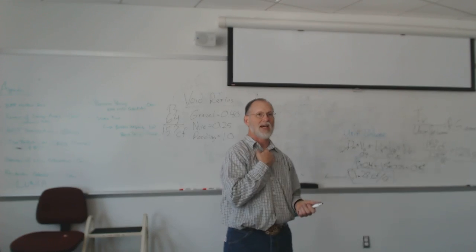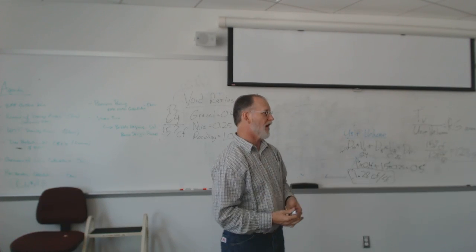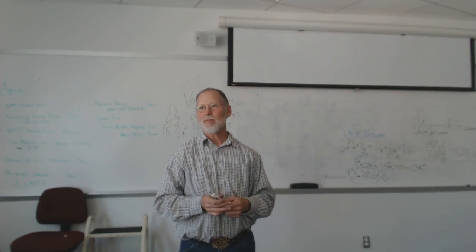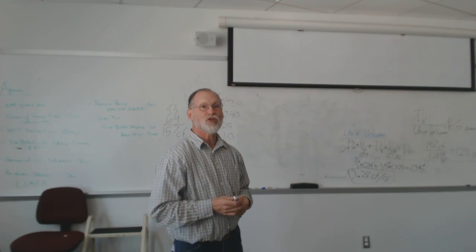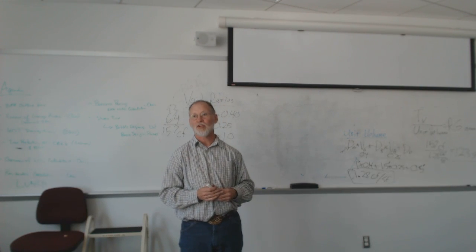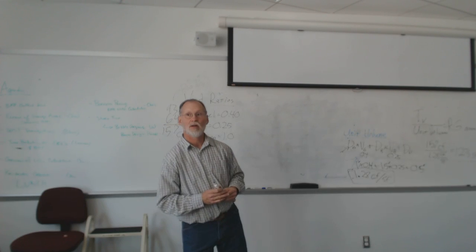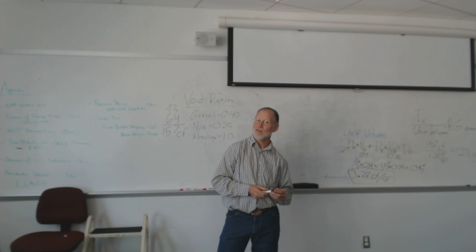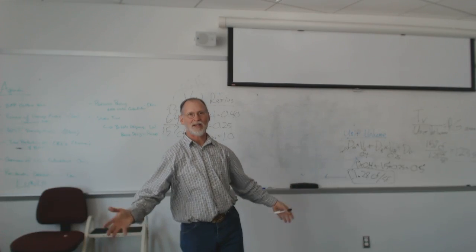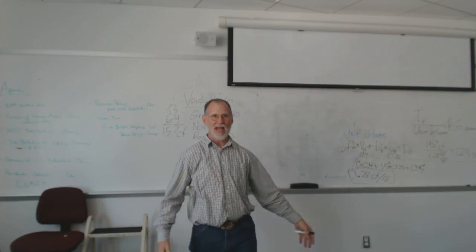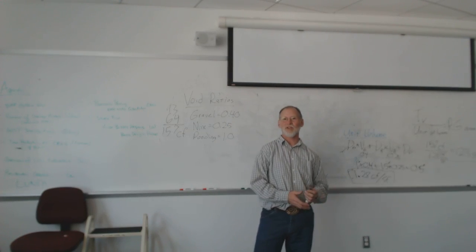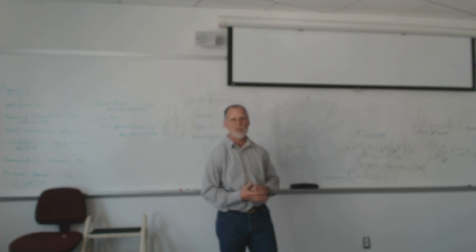So you're talking about projects like I'm working on right now, that I'm just starting the design for, my new shiny job. They haven't fired me yet. We're probably going to be looking at 5 or 6 tractor trailer dump loads of bioretention mix, hundreds of cubic yards of mix. Where is it? It's in Louisa, of all places. So it's actually a very unenvironmental site. It's an industrial park, and they're flattening out a big pad and doing a lot of pavement and buildings, but we've got to manage the stormwater. And so we're using a series of rain gardens and level spreaders.